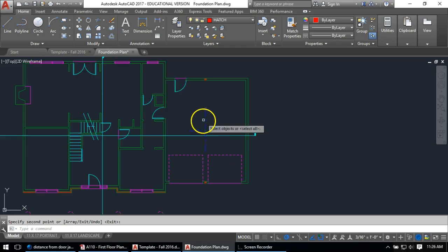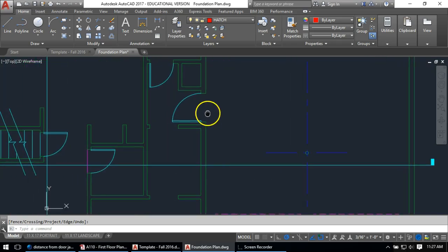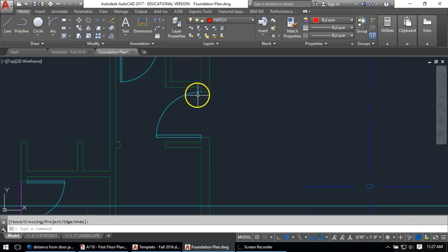In this particular drawing, the center line of the vertical one's from top to bottom, so I'll just extend my line up to do the same, but this one is short, so I'll leave that one short. Oh, and I should note I've got a little set of stairs here. There's no detail on how wide those stairs are specifically. They're bigger than the 3 feet clear needed. We can see that because they look like they probably align with the midpoint of these walls, which is marked at 4 feet. So let me draw a line just here.